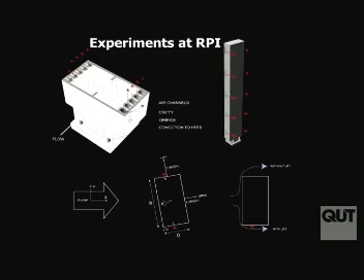Here's an example of our model. It's a 15:1 aspect ratio, 2:1 plan aspect ratio building, where we had the ability to inject flow at various levels on either side of the building. So it's a way now of not changing the shape of the building, not changing the stiffness of the building, not adding to the damping of the building, but to use the resources of air conditioning the building to improve the structural performance of the building under wind loading.